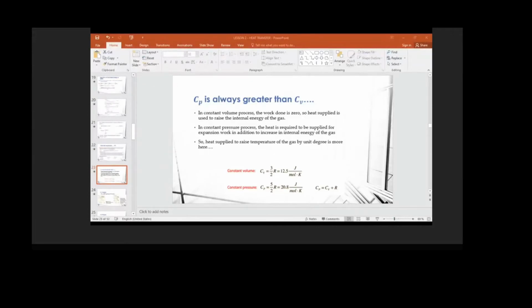But if you take, for example, a container that, when you apply heat to it, is going to change volume first, because that's the first thing that any object that can change volume will do, it's going to change the volume first, and then it's going to use some of that energy to actually change the temperature. So you need an excess amount of energy to change the volume first before it can change the temperature. So that's why Cp has a greater value than Cv.